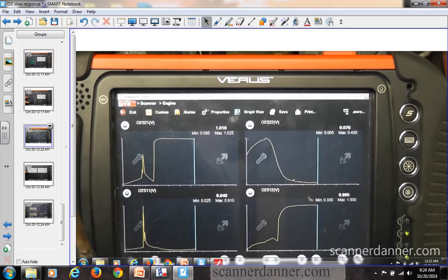If we look at the bank 2 sensor 1, so this is the same Isuzu, I think this was an Isuzu, right? Is that this case study where the 2 upstream sensors were reversed? If we look at the bank 2 sensor 1, what's it reporting? It's reporting a rich condition. I can't really see that myself. What about blue? Is that better? Yeah. So bank 2 sensor 1's reporting a rich condition, and I want you guys to notice at the same time that we're actually reporting a lean condition downstream.